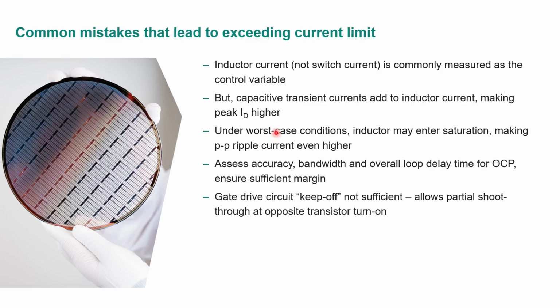When you're at the limit of maximum current that your power supply or converter is designed for, usually to save money, the inductor is designed to approach saturation at that point. So you can end up with a condition where the inductance is dropping and current is rising even more quickly. It's a positive feedback loop that rapidly accelerates the rise in current.